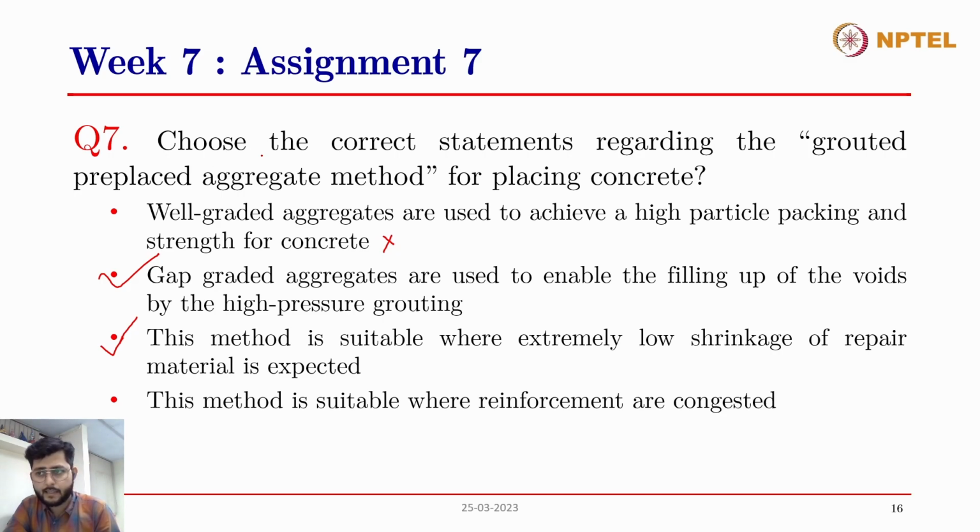So essentially, if we had been pumping the concrete instead of the grout alone, then we would be going with the well-graded aggregates because well-graded aggregates will enhance the particle packing of the concrete, and therefore that repair work will be achieving the goal that is expected out of it.